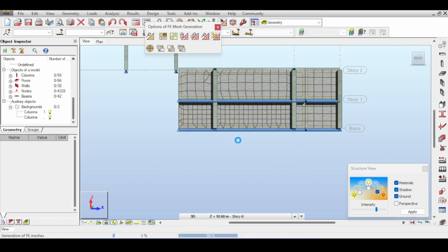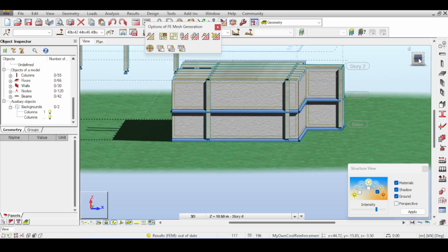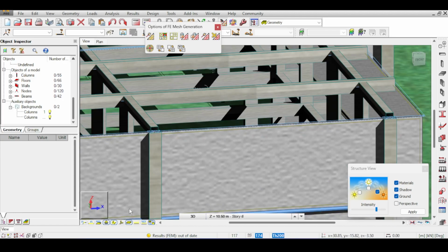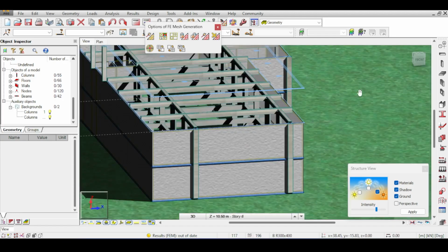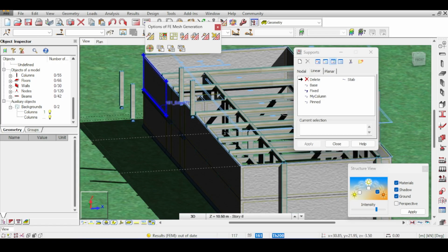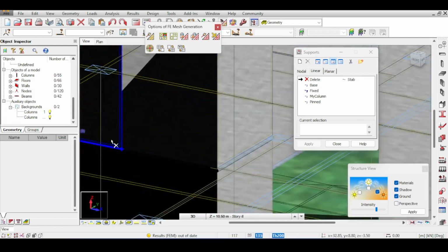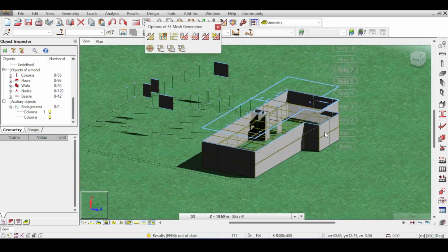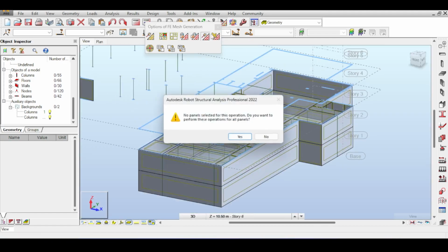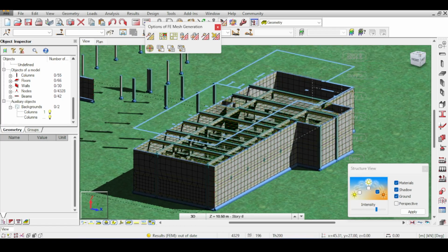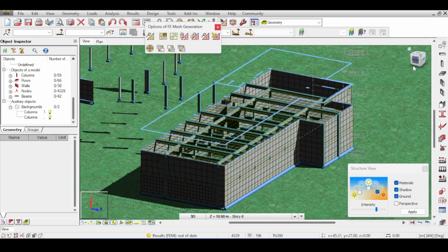Okay, let me delete the mesh first of all. Okay. It seems I have some supports. Remove the section. No supports. Okay, I have supports for walls. This is incorrect. So I go to support, click delete, and start deleting those supports. Okay, so I think now we are correct, I guess. So from what I'm gathering right now, I just want to generate the mesh. Yep. I think the modeling of the basement is complete with exception to the staircase and the car ramp. This will come in later stages, but the basement itself has been accomplished.